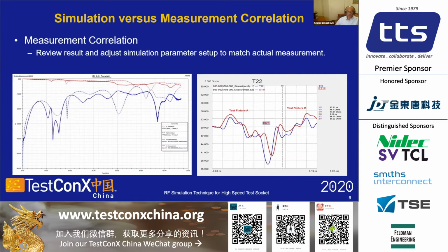All this can make some little variation between the measurement and the simulation. You do that by optimizing the impedance curve, and then you find the electric constant property of the material, and then you feed those back to the simulation. You will obtain a more accurate simulation result.